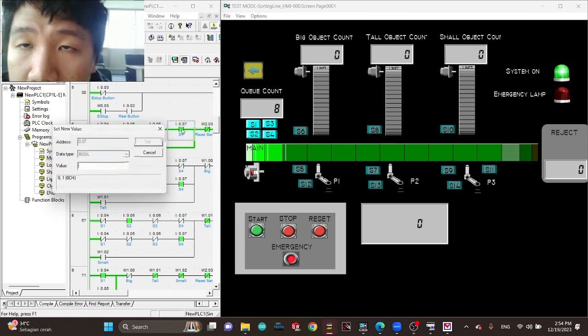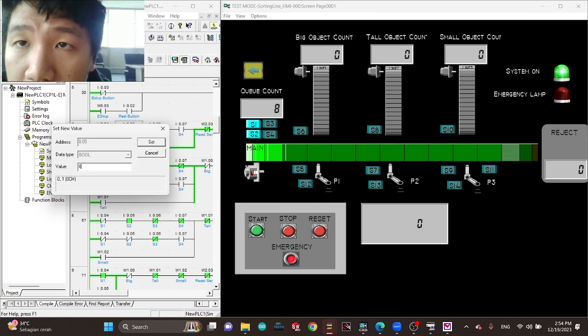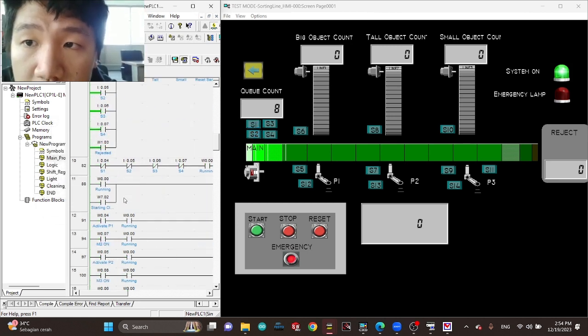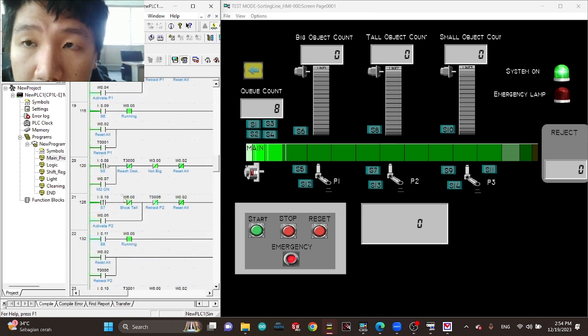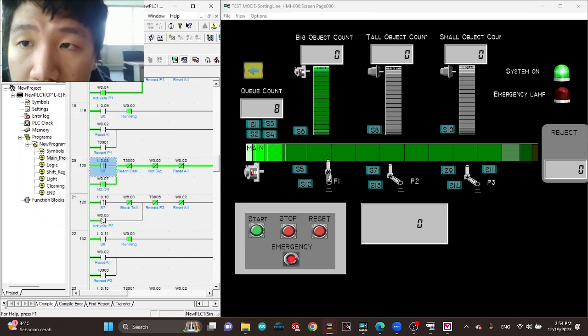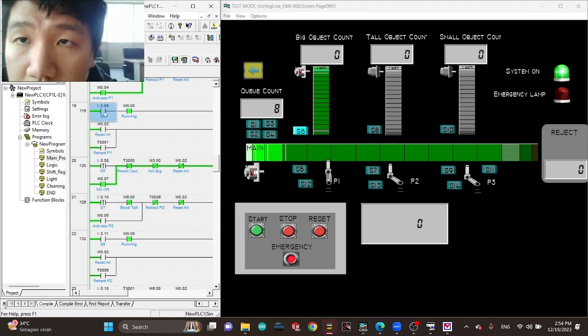As you can see, the sensor detects it, and it will give the output after the item leaves the sensor, which means that after all of the sensors turn off, it will give the input that it is a big item. And then when it passes through S5, it's going to be pushed. At S5, it's going to be pushed, meaning the item won't be detected by S5 anymore, it turned off. Then the item is pushed to the conveyor, meaning S6 will be turned on.